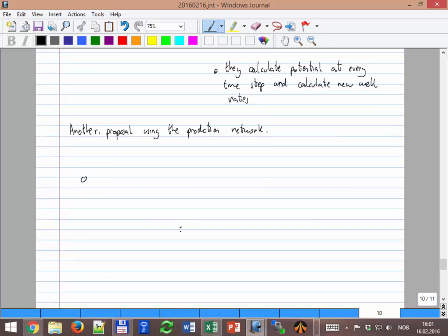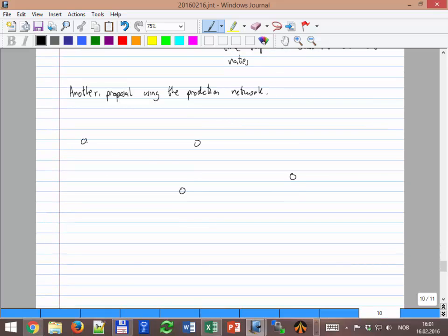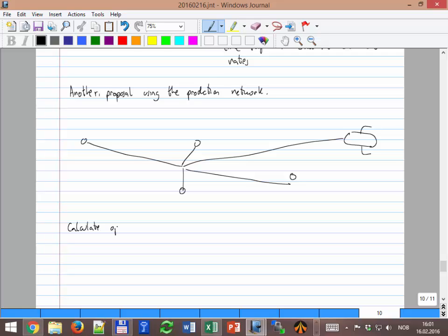Let's say you have again the same wells, 5 or 4? 4. You commingle them together and then you have a network, and then you calculate open choke rates. You first have to bring the IPR from the reservoir model. Then at that point you run an open choke simulation. You calculate the equilibrium open choke rates, and we call that QI, open choke, OC.